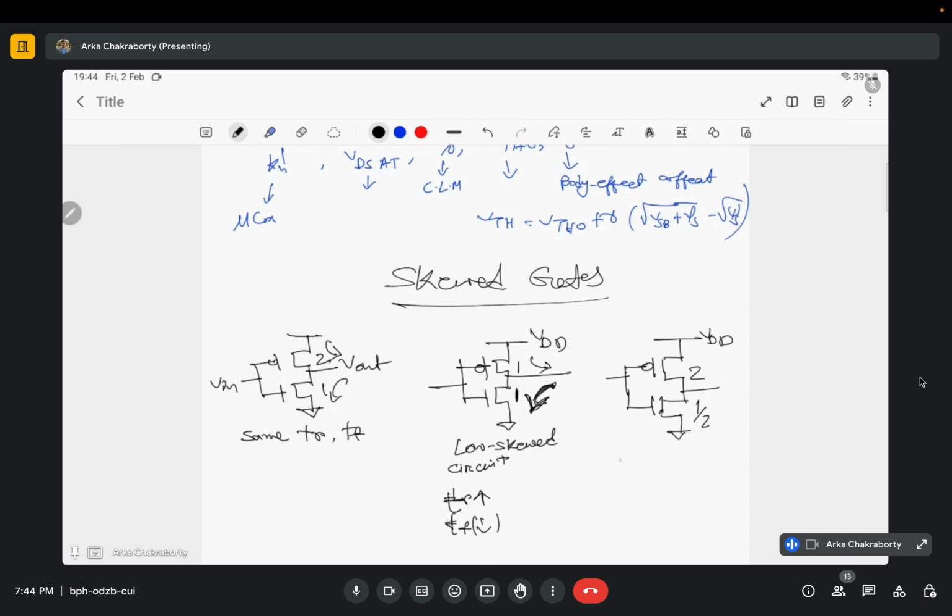So here my rise time will be reduced, but my fall time would increase, because my charging current has become much higher compared to my discharging current. So one of the delays will go up and one will go down depending upon my application. I can design skewed gates as required. Skewed gates were in your discussion topic, that's why I thought of including it.